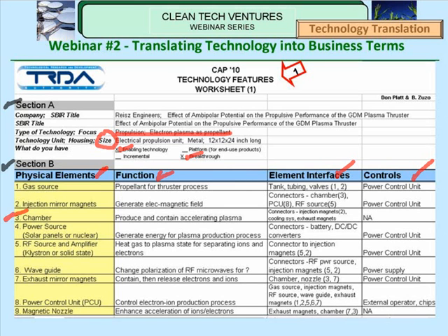The chamber is the part of the device which produces and contains the accelerating plasma. It's connected to an injection magnet. And the injection magnet helps to accelerate the particles. There's a cooling system to take heat away. The process gives off heat, and there's some exit magnets. These exit magnets help to control the flow of the exhaust particles through the nozzle.